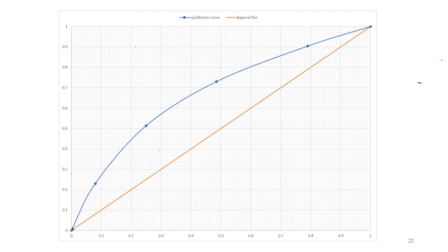Okay, now that you know your ROL and Q line, the points for your ROL would be XD. XD in this case is 0.97. 0.97 is 1 point. So you can put that one here. And also from the equation just now, when x equals 0, y equals 0.277, so you can mark 1 point here at almost 0.28.